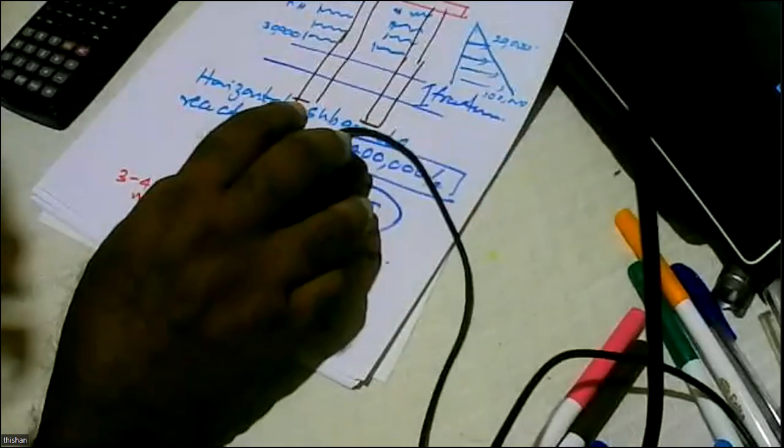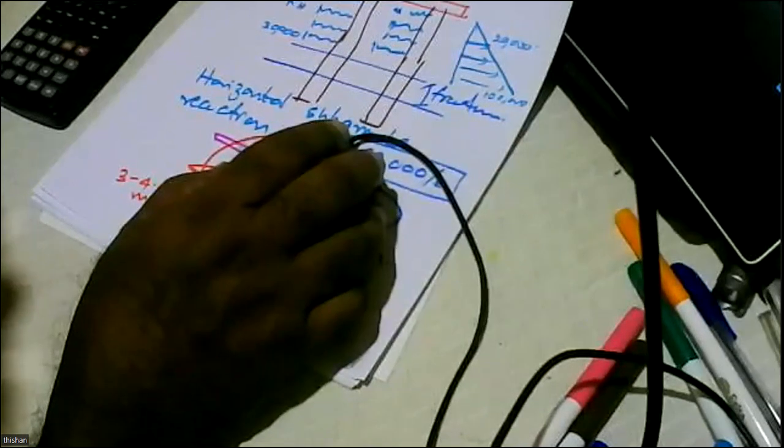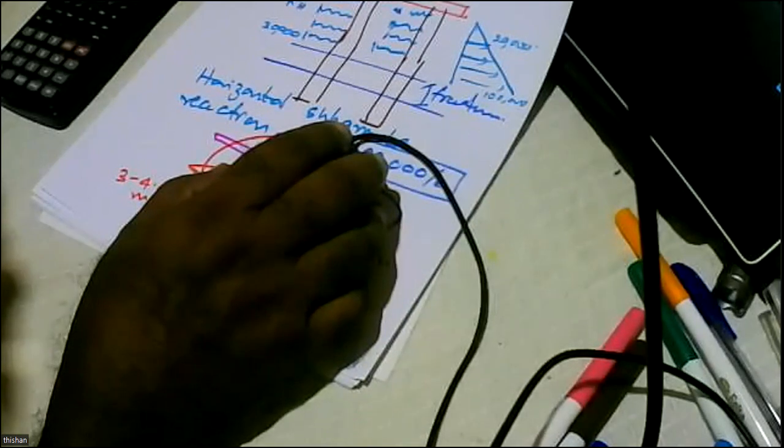Yes, sir. There was one question in the chat box. What do you think about reducing the pile length based on bored pile sample with higher point load? Can the pile group be the same length to avoid differential settlement?